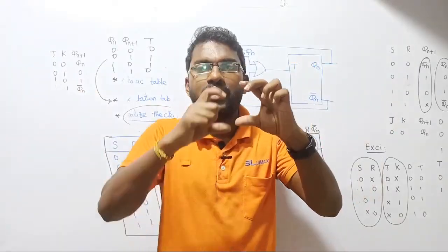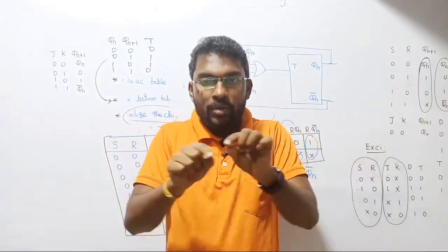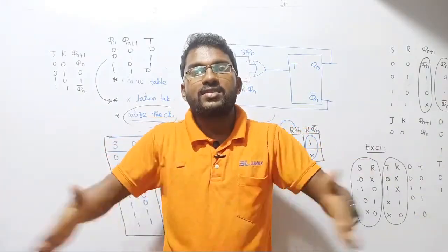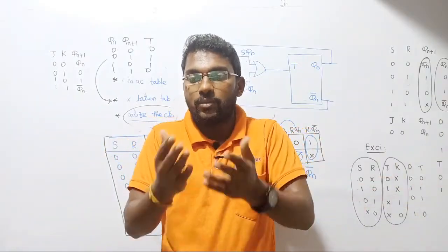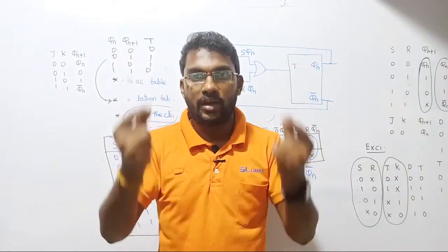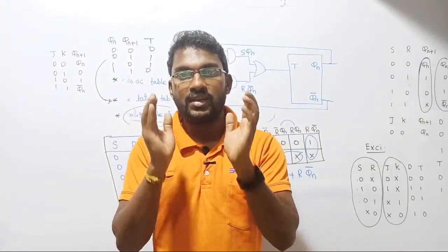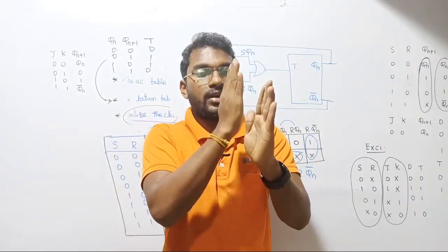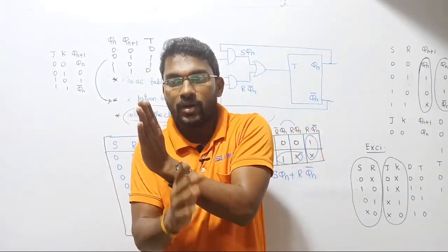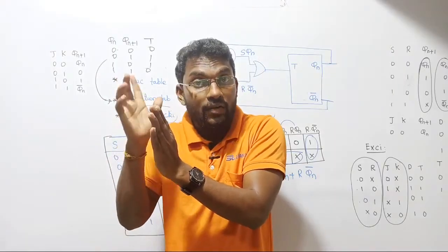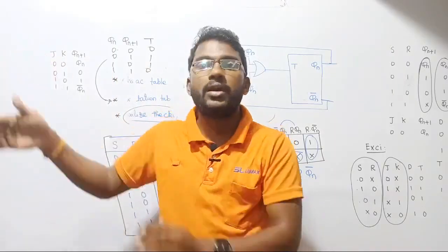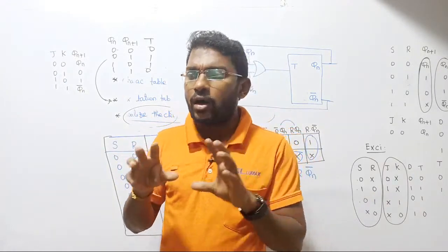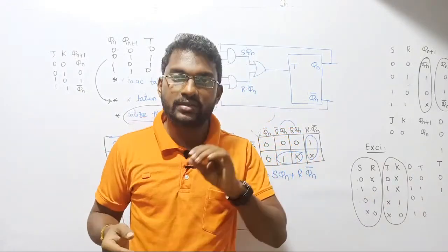In synchronization, you can simply treat your train as a common clock pulse. All boxes are synchronized together, running at the same speed, and triggered at the same time. But that is not possible in an asynchronous counter. In an asynchronous counter, first we consider one flip-flop and then another. The second flip-flop is triggered with the help of the first flip-flop, and this sequence continues. So we cannot give assurance that all flip-flops are always working together in an asynchronous counter.